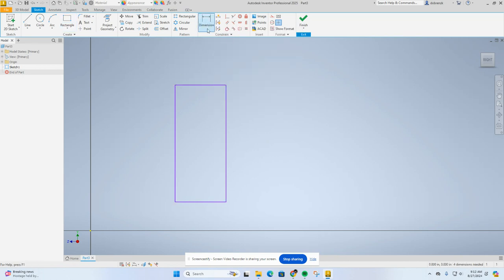The best way to use the dimension tool is to click where you want the arrows to point. So if you look, I click those two lines and I have this 0.314 because that's the current size of this, and the arrows don't change no matter where I put them. I could go all the way up or all the way down. For the purposes of this assignment, I want you to replicate the general area where I put my arrows. It's important when you're dimensioning things to not have too many things overlap and confuse the person looking at them. So you want to space out your dimensions.